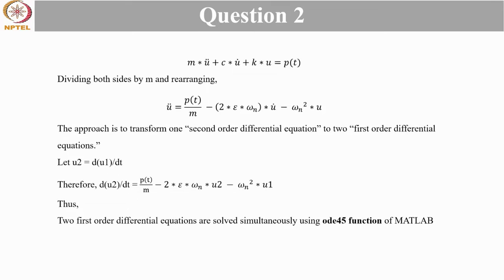Now, again, we will require the assistance of MATLAB for solving this problem. Why? Because it is a damped forced vibration, which is a little bit complex. A second degree ordinary differential equation is very difficult to solve on pen and paper. In the last session, we saw how to write code for a damped forced vibration in MATLAB. We will first define a function. That function will yield two values: the velocity response and the deformation response.